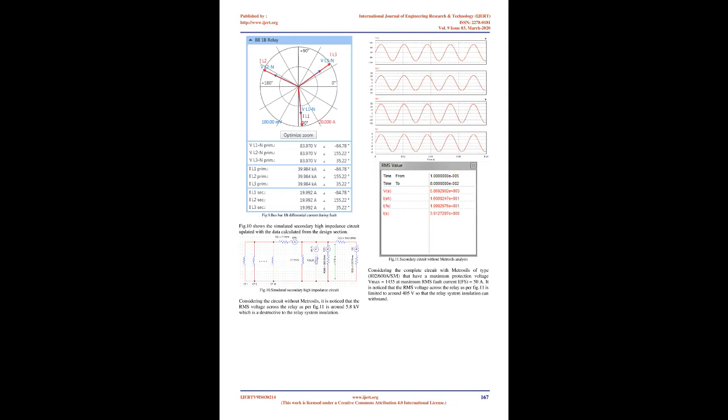We can consider that there are disturbances if the primary differential current is more than or equal to 125 A or 10% of the CT ratio of the lowest load current bay, whichever is the greater.